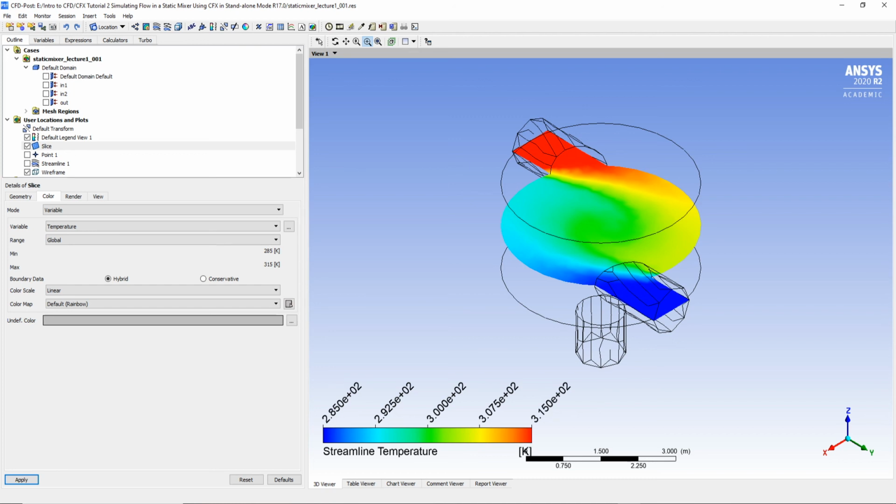You can also do something to get more detail out of this plane. So what you can do is adding a contour instead of using a plane. A contour connects all points of equal value for a scalar variable, for example in this case temperature, and helps to visualize variable values and gradients. Okay, so color bands fill the spaces between each contour line, and each band is colored by the average color of its two bounding contour lines. Okay, so let's create a contour.